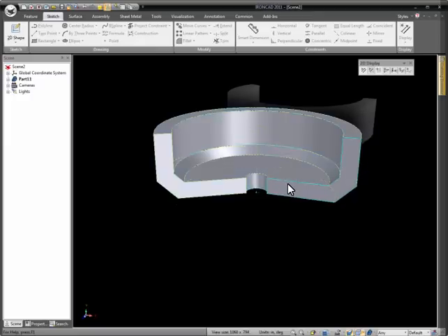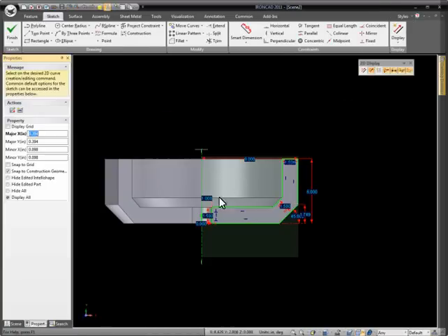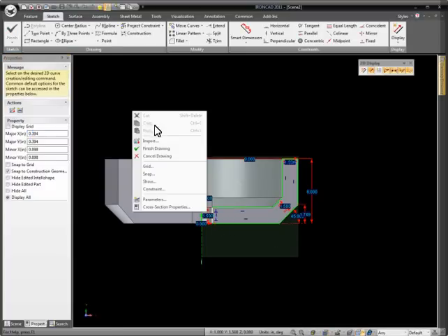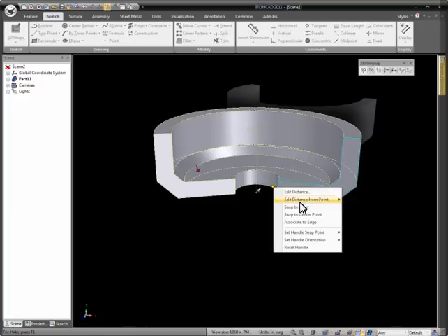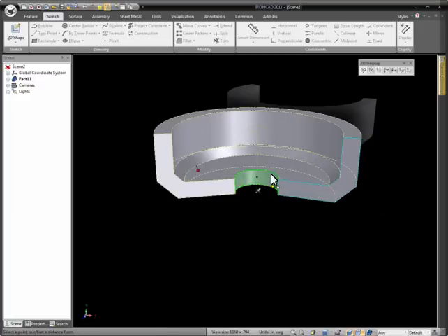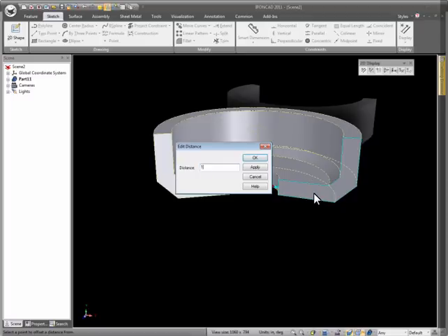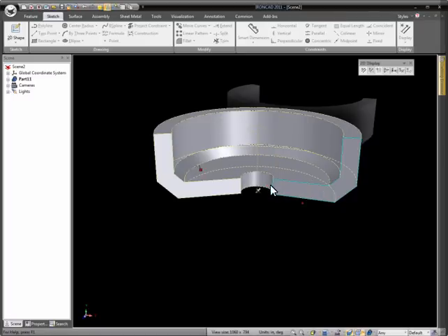If you go back into your sketch, we can say, for example, we just unlock one of these constraints. Now notice this one becomes ungreen. It's actually white again. If we go back and finish our sketch, now this handle is able to be adjusted. So if we wanted to allow the user to dynamically adjust the elements, you can create the unlocked sketch information inside of here. And they can actually use any number of tools. For example, maybe you want to set the distance of this guy from the center, back to 1.5. They can adjust that using the handles as well.